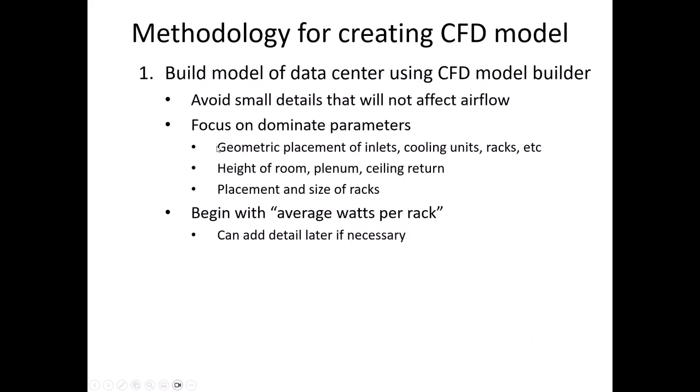So we're going to use these to model a data center or to review a data center. So the way we'll do it is to build a model. We've already built it. We're going to use CFD to build it. We're going to use CoolSim. And a few notes about creating data centers. Just again, for new users or my users, avoid small details. It is not a CAD system.